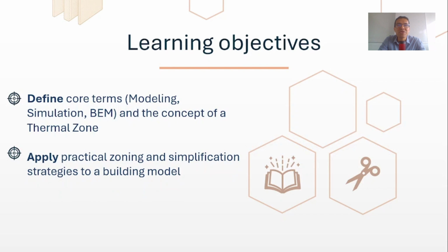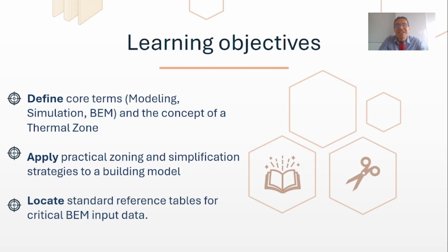Next, you will be able to apply practical strategies for building your model. This means knowing when it's smart to group several rooms into a single zone to save time, and when you need to simplify the geometry of an imported file to maintain accuracy. Finally, you will know how to locate the essential input data required for any energy simulation. We'll show you exactly where to find the reliable industry standard reference tables for things like material properties, internal gains, and standard weather files.